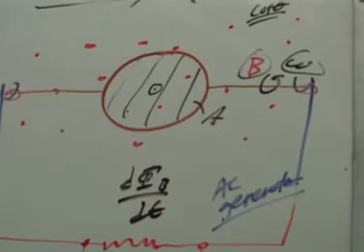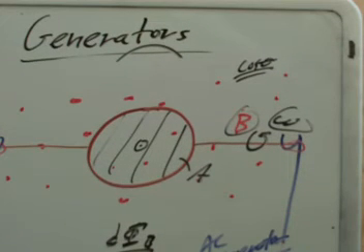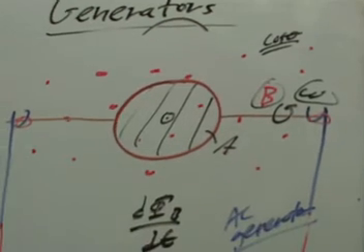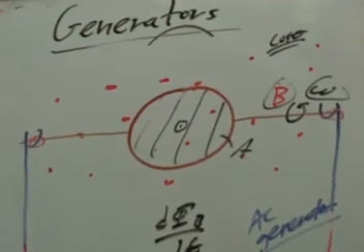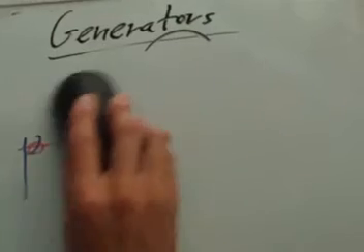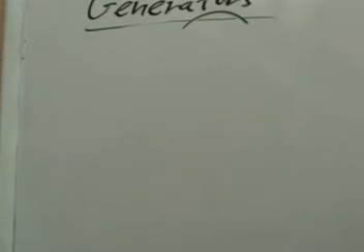So an AC generator, letting that theta change relative to everything in the problem, relative to the B, relative to the A, is really a nice example of a direct application of Faraday's law about how just spinning a loop in a magnetic field is where electricity comes from. And just two more things on that. Where does the spinning come from again?